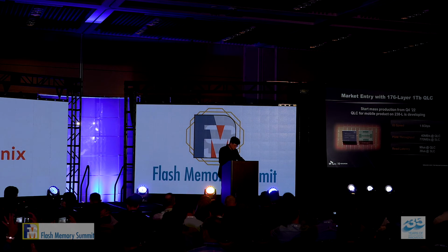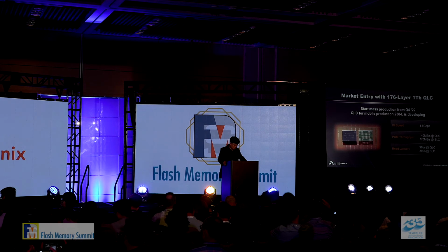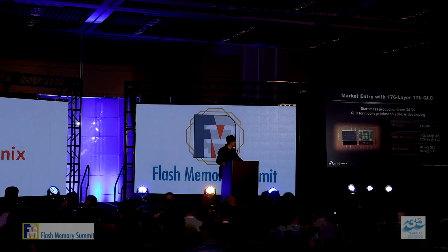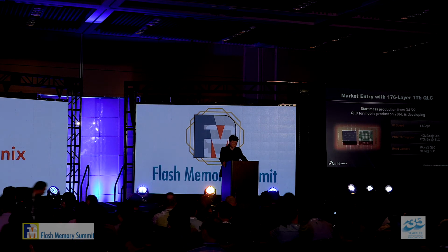With the continuous enhancement to the 4D NAND, we have also readied the QLC lineup. Our latest is the 176-layer 1 terabit QLC, which has been delivered as commercial samples since last June. We will start mass production from the fourth quarter of this year with the performance spec as shown in here. Based on 176-layer CTF QLC technology, we are developing 238-layer QLC that can be used in mobile products as well.